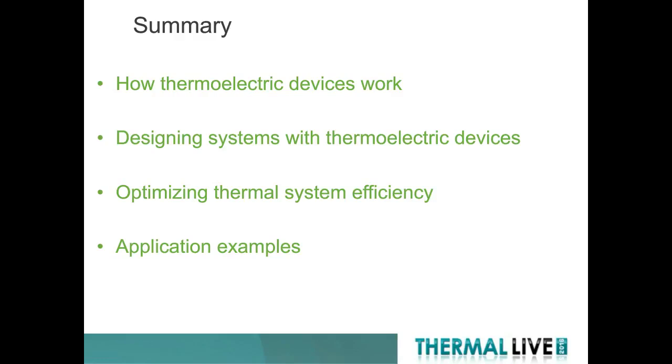And then the other big question is the range over which you thermocycle or power cycle these devices. The larger the range, the larger the delta T you set up, and this will lead to a higher stress and can cause failures in devices.